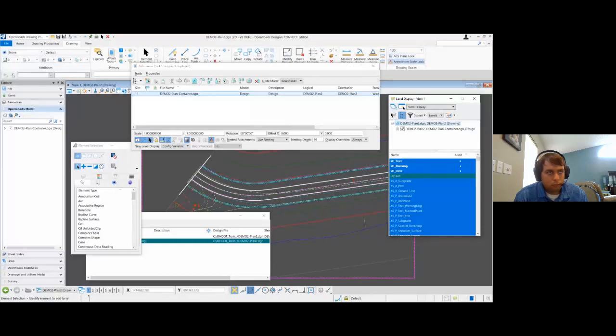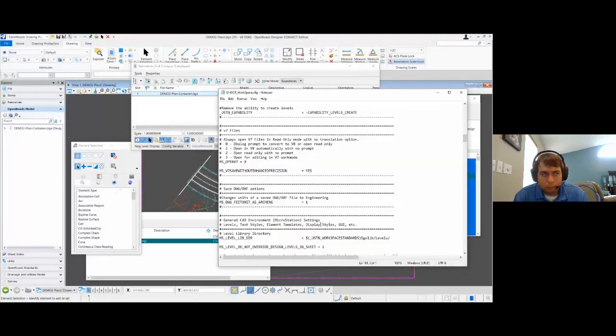So I wanted to quickly show how that's working. What I would like to do is turn off the variable first and then turn it on later and show you how it really is coming into play here. So I'm just going to turn it off. Since it is on in our workspace, we don't recommend changing the workspace config file. So what you could do is, inside your workset config file, just set this equal to nothing.